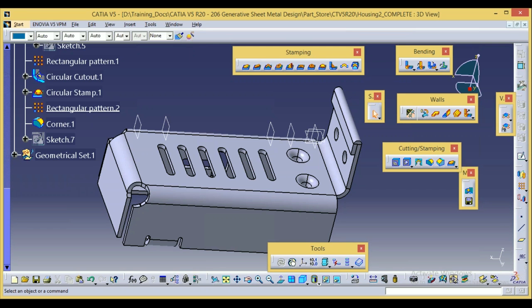Even the bonnet and all these things are made of sheet, but I think they won't use sheet metal for that. Those are like mold-like things, or they'll weld inside bosses. For snap fitting, they'll have some fits. They won't be doing these in sheet metal. Maybe they'll use some forming techniques, hydroforming or something, and rolling. Sheet metal processes they will definitely do for getting the shapes.